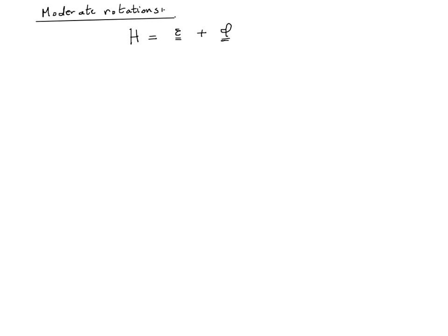But sometimes the displacements are larger without having significantly larger strains. So we have larger displacements, so H is not very small, but the strains are small. And in that case, the increasing magnitude of H can only come from rotation.